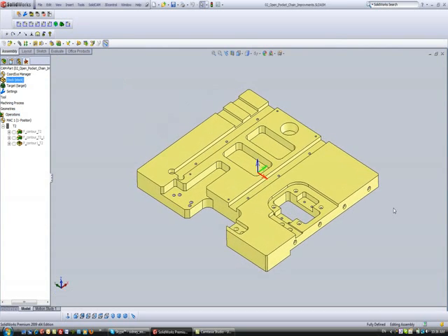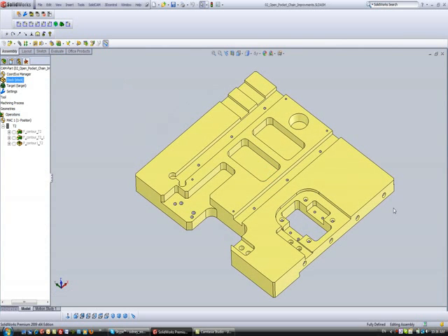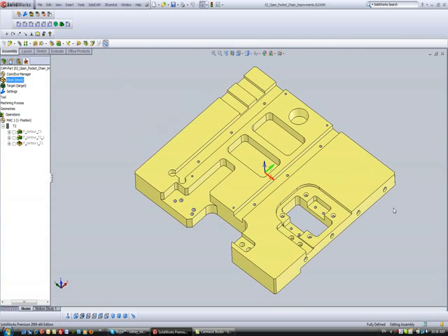Now in this part that we see on our screen, I'd like to show some tips and tricks and how to use our geometry selection for slots such as this or this area over here, and also to show some of the ways of using an open pocket such as this pocket over here. We'll start off by showing you this area over here. If you'll note, I'd like to machine it by simply going across this way onto this chain over here and continuing on this way without going into these areas at all.